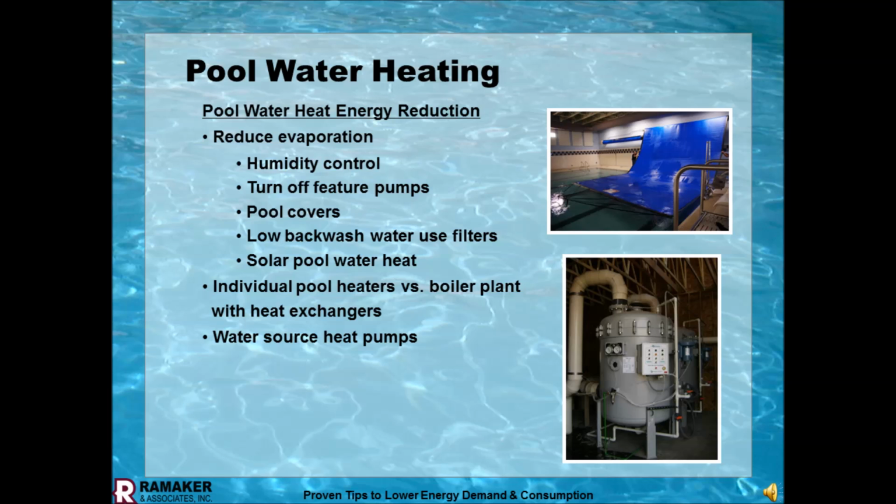Significant reduction in it, and it helps not only, again, heat, water, and chemicals, but in a few places we have worked where we have downstream lift stations that don't have the capacity to handle a backwash rate of that size, and doing the regenerative filter, reduced backwash, we were able to hold that without putting a 10 or 15,000 gallon storage tank out below grade.